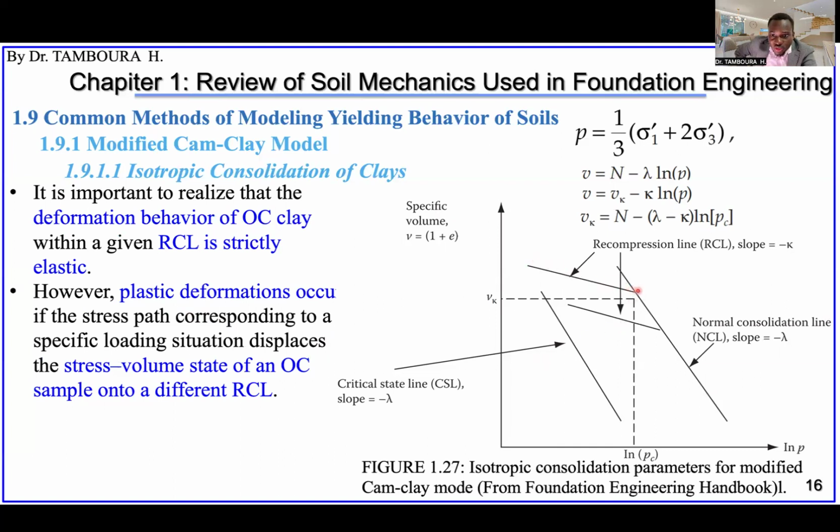If we go above this point, we enter plastic deformation. It will not be elastic anymore. This zone will be plastic. Do you understand the difference between elastic and plastic? Elastic means you can still recover the deformation. But if you enter here, you will not recover all the deformation you cause.